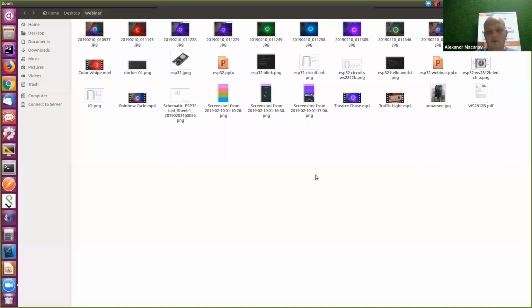What is the value of the config minimal stack size? I'm not actually sure, I haven't checked, but from what I know, it's the minimal size of the stack that you need in bytes for a single task. So you cannot go less than that. A good idea would be to check the documentation if you're interested. Personally, I haven't checked. When I don't use this constant, I use something like 1024 or 2048.